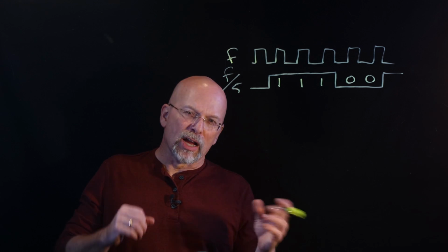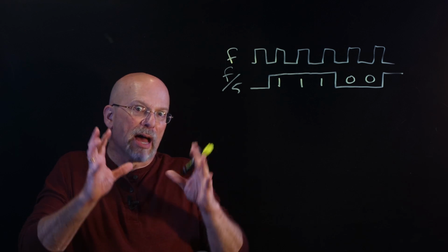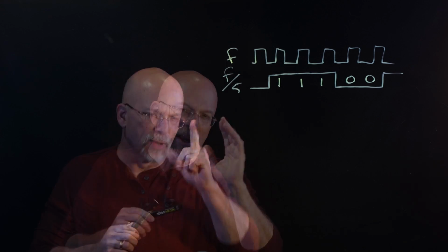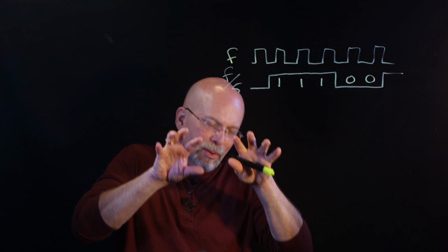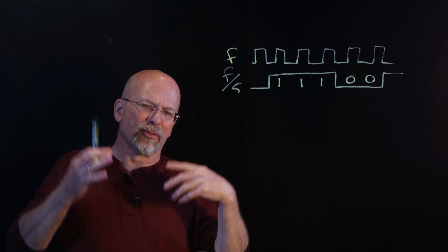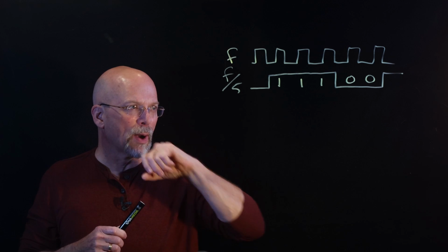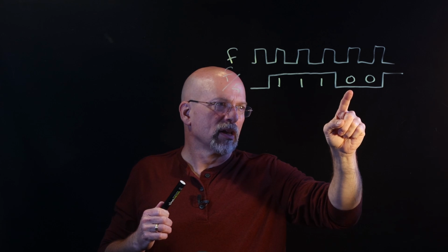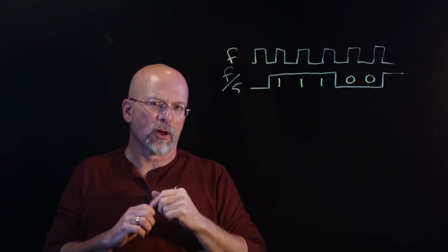We're going to go through a design process similar to what we discussed when we talked about the linear feedback shift registers, where we were talking about shifting values through, and the last flip-flop is going to output that particular value. Now remember, the shift registers meant that the contents of those D flip-flops moved one position to the right with each clock pulse. But we also had a discussion about the number of flip-flops that were needed based on the number of states that we needed to represent. And in this case, we have 5 states that we're going to need to represent. The first one, second one, third one, first 0, second 0. So there's 5 states. Now remember, we need to have enough flip-flops to represent all 5 of those states.